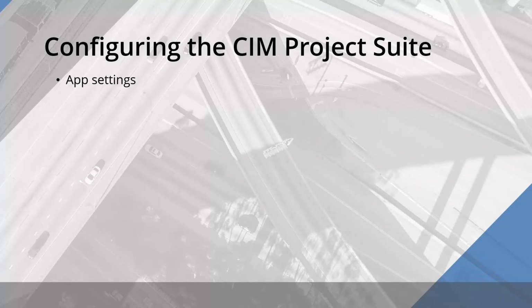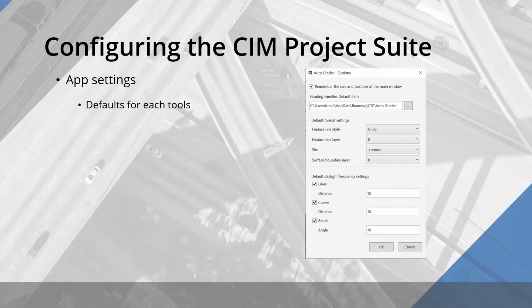So configuring the CIM Project Suite, there's three kind of major categories I want to touch on here. One is app settings. This is default behavior for a given tool. Take one of the tools like AutoGrader. What are the default format styles, like default feature line styles? There's some settings in here about when you're doing surface targeting with AutoGrader. What are some of those default settings? You have similar kind of stuff in the settings tab of Civil 3D.